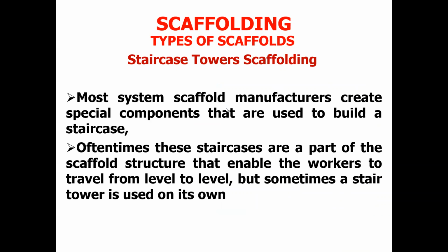Another type of system scaffolding is called staircase towers scaffolding. Most of the manufacturers of system scaffolds usually create special components that can be used to build a staircase. Just like you saw in what I just showed you, a quick stage scaffolding has a staircase component. Hackey scaffolding has a staircase component.